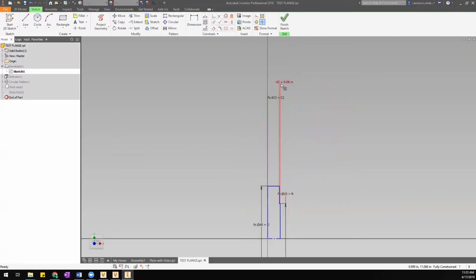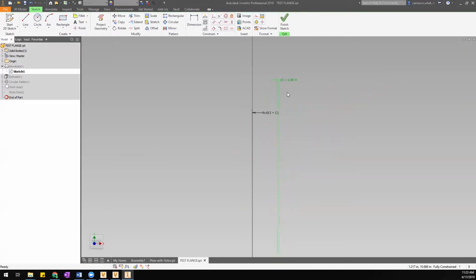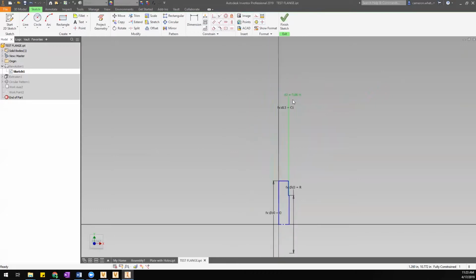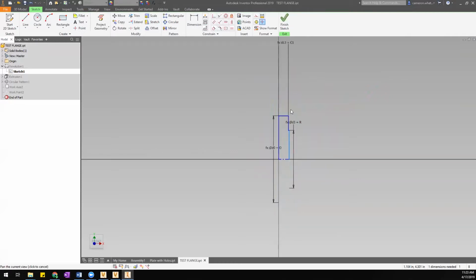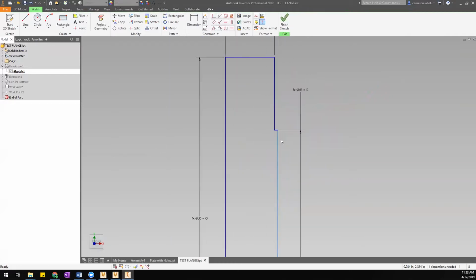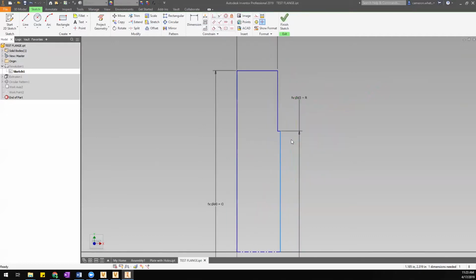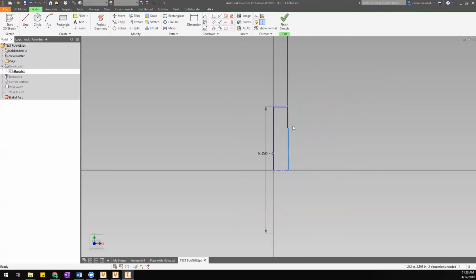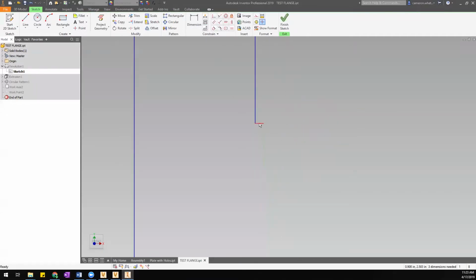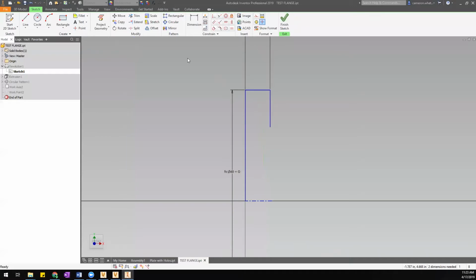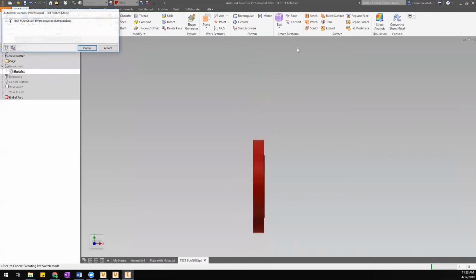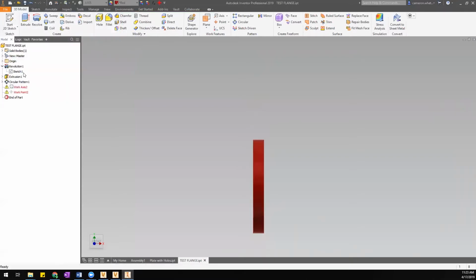And there's a couple of parameters associated with that. Oh, that's just a user parameter. It's not a named parameter. So I have no qualms about deleting that. And this R, that's going to be the diameter of the raised face, which is not going to apply anymore. So I'm okay deleting that. I'm going to delete these 2 lines and repair my profile by reconnecting those endpoints. And the revolve solved just fine.